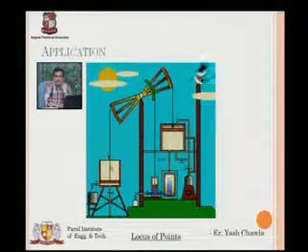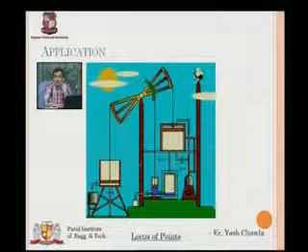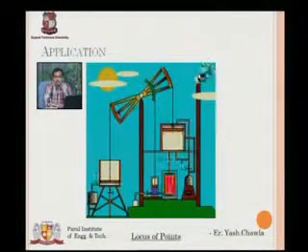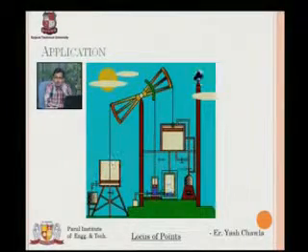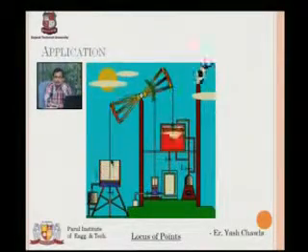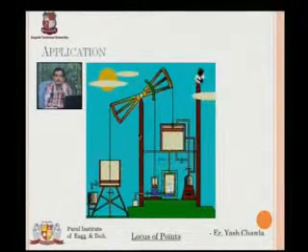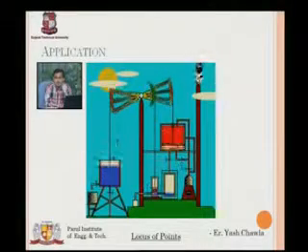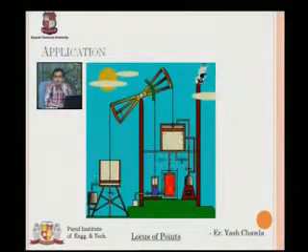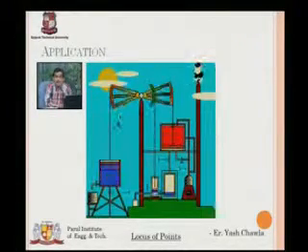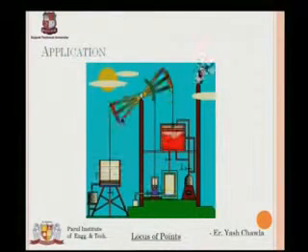And what is this? This is a slider. Both these are sliders. What they are doing, they are moving according to this particular crank because this is the connecting rod that is making them move. So this is an example of a slider and crank mechanism. This is the crank which is oscillating, this is the connecting rod, and this is the slider which is oscillating. So this is the slider, this is the connecting rod, and this is my crank.